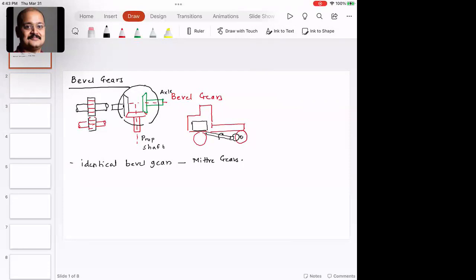Now at this time, before I give you the outline for the design steps, I want to ask students the question, how would we design a bevel gear? Yeah, go ahead. Just a helical gear or a spur gear at an angle? So what you do is, again, the same concept. Take the bevel gear, convert that into an equivalent spur gear, and follow the same process.